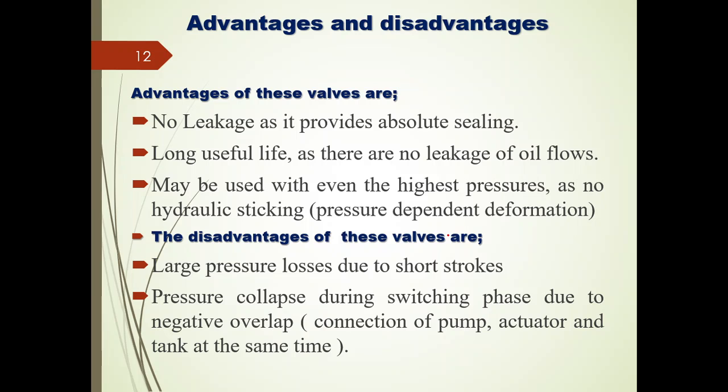Some of the advantages as well as the disadvantages we have. The advantages are no leakage, as it provides absolute sealing. Because of the tight sealing, we will not be getting any leakage. Right. The longer useful life, as there is no leakage of the oil flow, and it may be used even with the highest pressure, as no hydraulic sticking. Right. So there will not be hydraulic sticking, because of which it can even operate at the highest pressure.